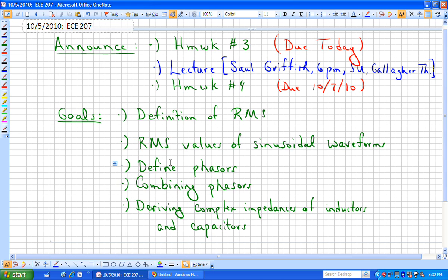And if we're exciting a circuit with a sinusoidal waveform of a given frequency, omega in radians per second, we'll see that frequency all over in our linear circuit. The voltage across the resistor will be operating at that same frequency. Because we are dealing with linear circuits, all of our currents and voltages will be oscillating or moving back and forth at that same sinusoidal frequency.